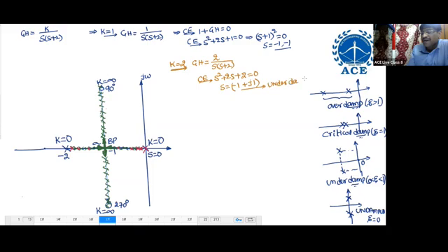You take K even 100, also underdamped only. K 100 means S square plus 2S plus 100. What are the roots? -1 plus or minus j root 99. The real part -1 never changes. Only the imaginary part is going to change. It may be plus or minus j1, plus j99, or plus j infinity. System is going to become underdamped. So that means you take any value of K greater than 1, the system is underdamped.